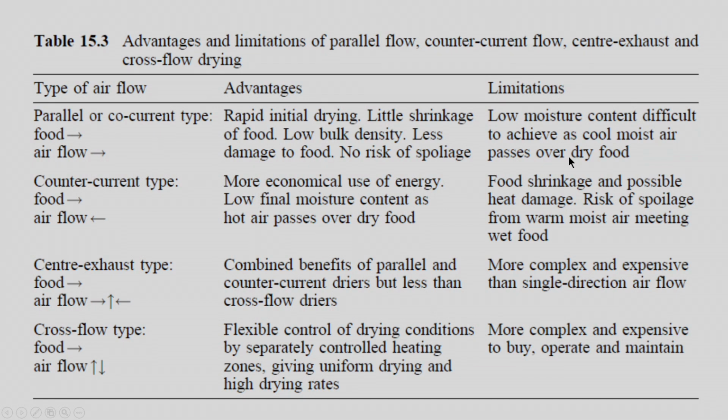Okay, so here are the advantages and limitations of different flow configurations. It can be done in co-current, counter current, center exhaust and cross flow type. If food as well as air flow is in the same parallel or co-current mode, one thing is that low moisture content is difficult to achieve as cold moist air passes over the dry food.